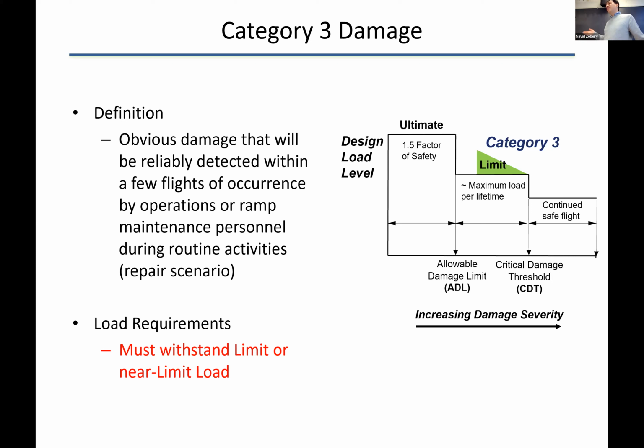So you're flying, or it has happened, the aircraft flies like a day, 2 days, 3 days until the next inspection cycle. It can still survive that. But if you do it 40 years, and in that 40 years, all of a sudden there's an extremely large load, it might not survive it, right? So if fatigue and large load comes together, the aircraft is not designed for it. But if you put aside fatigue, you have to show that it can carry the maximum load in the life cycle of the structure, which is quite severe if you think about it.